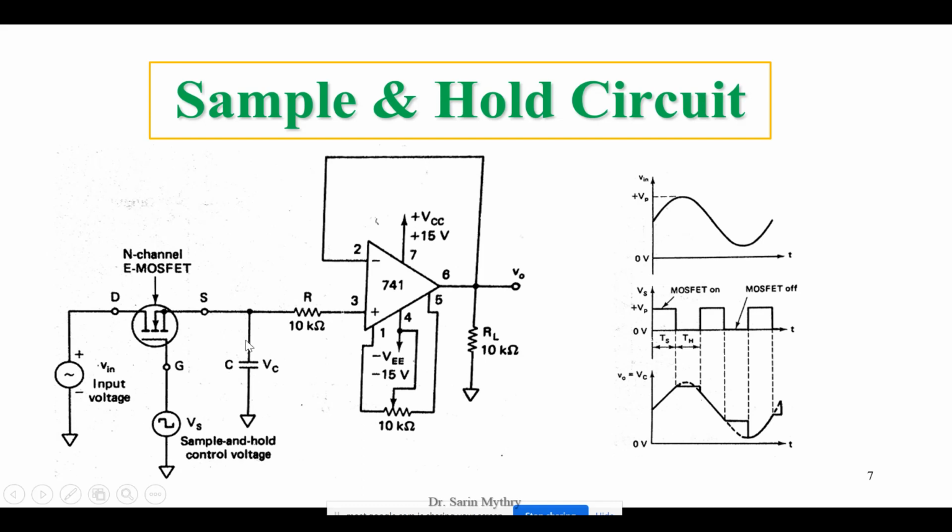And what kind of capacitor should we use here? We are supposed to use a low leakage capacitor. What are the examples of low leakage capacitors? They can be Teflon, T-E-F-L-O-N, capacitors, or else polyethylene capacitors. These are the low leakage capacitors.